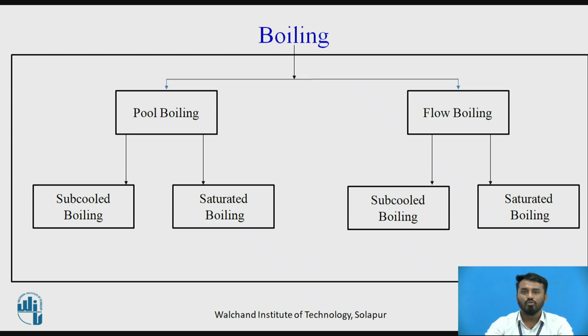Similarly, in flow boiling, we have two conditions as well. If the average fluid temperature is less than the saturation temperature at that particular pressure, then it is considered subcooled boiling. If the average temperature is greater than the saturation temperature at that pressure, then it is categorized under saturated boiling.